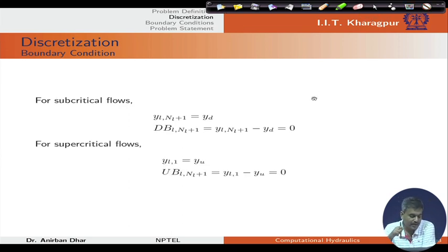But if we have supercritical flow, at the starting of the channel, at the first section itself, our depth is defined, then we will have the upstream boundary condition.